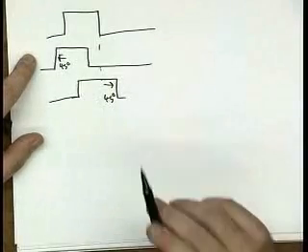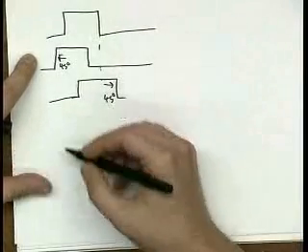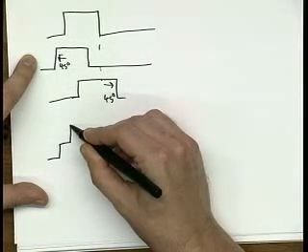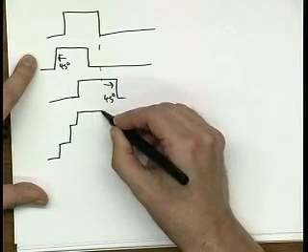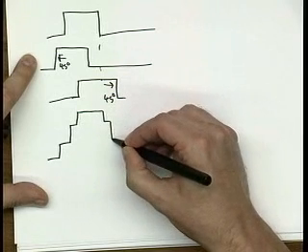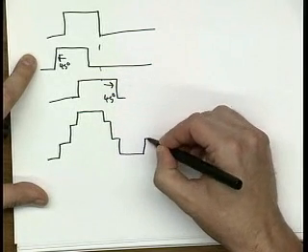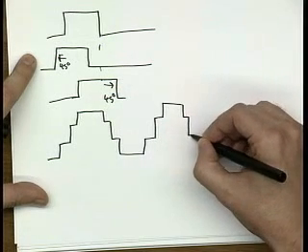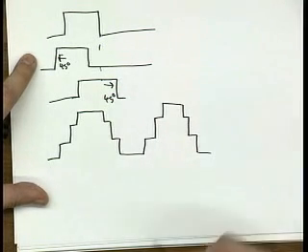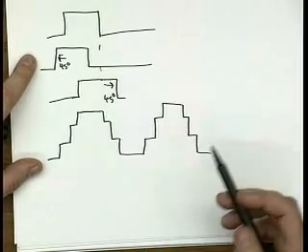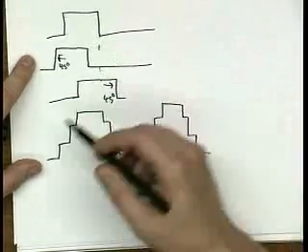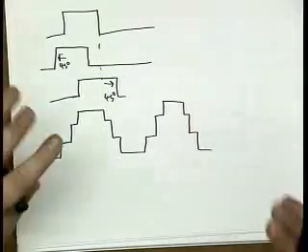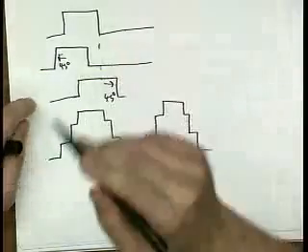Now, one thing I can do, if I just added these up, I would get a waveform that looked like, right. You can sort of see this is already more sinusoidal looking than a square wave, right? Looks closer. So one thing I could say is, well, I could add them up and then I could use this as my mixing waveform, my LO. But then we lose all the benefits of being hard switched. I mean, we're no longer sort of a binary thing.